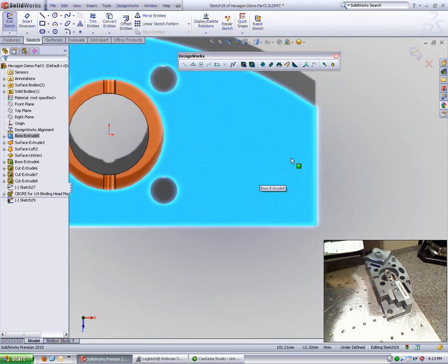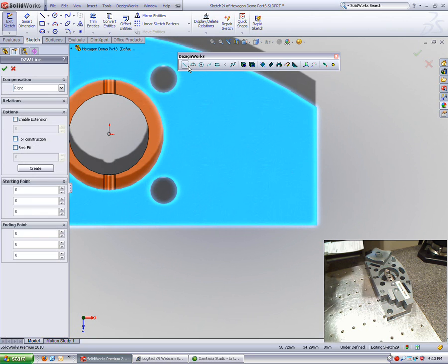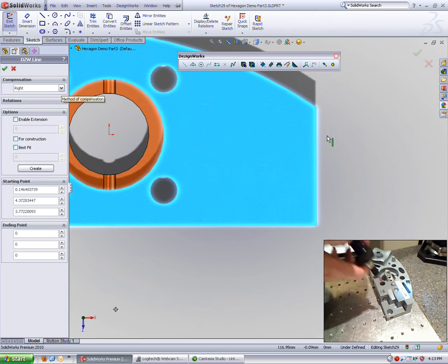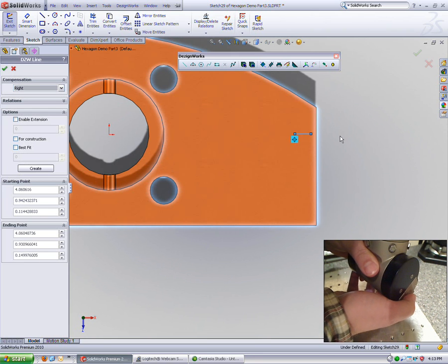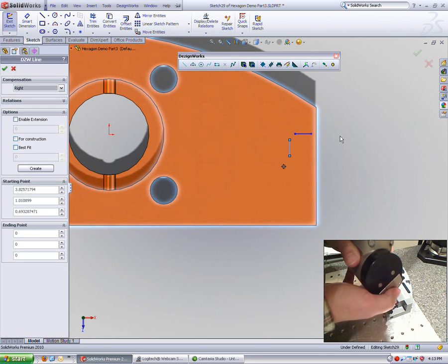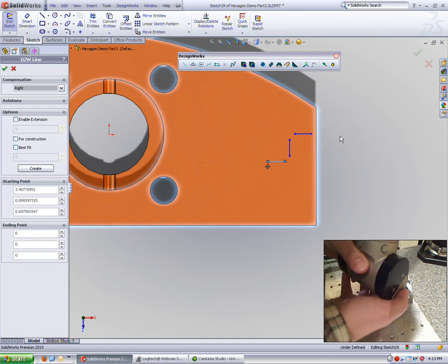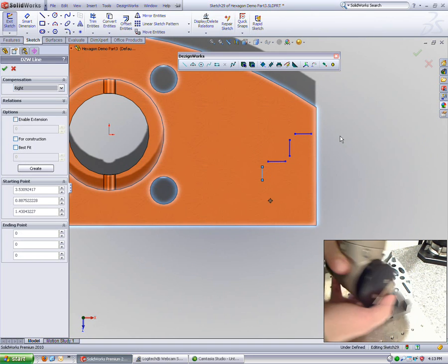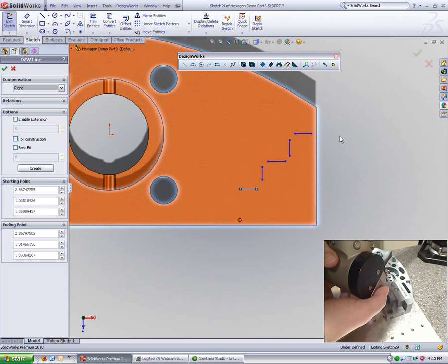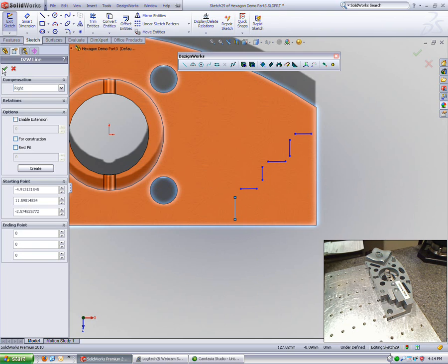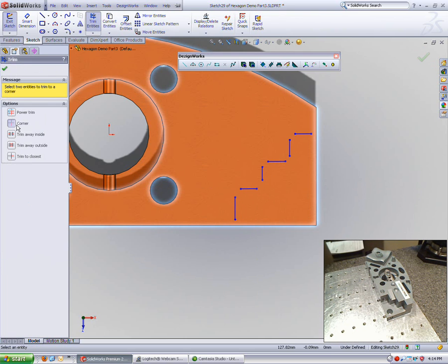The next set of geometry we're going to create is the steps along the right-hand side. This is also another example of doing some 2D sketching with some lines using the probe as the input. Here the nice thing is we're doing automatic compensation. We're doing a bunch of lines very quickly, or capturing a bunch of edges very quickly using the probe. And then we'll be able to step back again and use the SolidWorks tools to trim up that geometry to create some closed profiles.